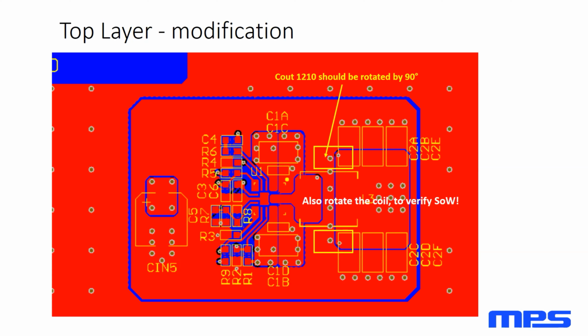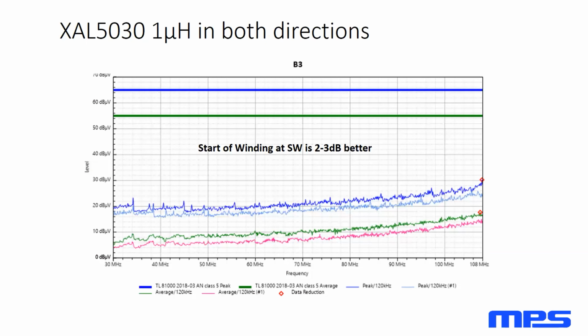All right, and then we had, regarding the inductor selection: I find that SRF is a useful figure of merit to consider. Once I've sorted for a range of acceptable DCR, saturation current, and the like, I sort for the highest SRF next because I want to minimize parasitic C between windings, which translates to less high frequency bleed through the part to the output node. Yeah, that's a comment, but it's a very, very good comment.